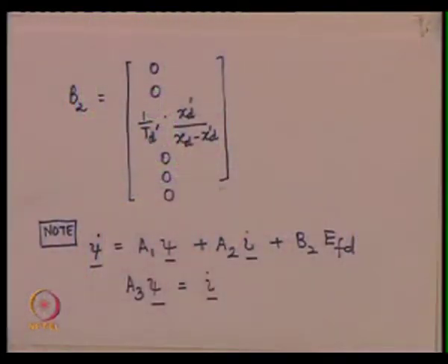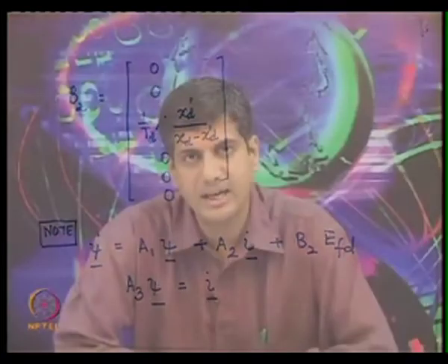If you look at the synchronous machine equations, in fact just the flux equations, since we are not considering the mechanical equation or the torque equations, the flux equations are in fact linear, and these transients can be studied by a simple linear system analysis, that is using eigenvalues and eigenvectors, and the complete response can be characterized and we can plot the response. We do not have to do a numerical integration because this is a linear system and the response of the system comes out in a nice closed form. So, that was what we discussed in the previous class.